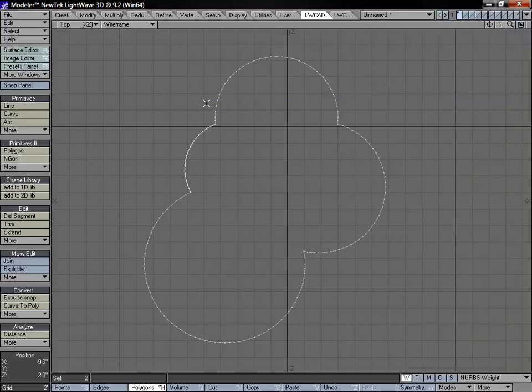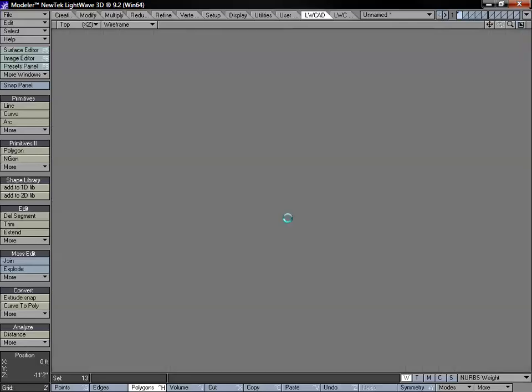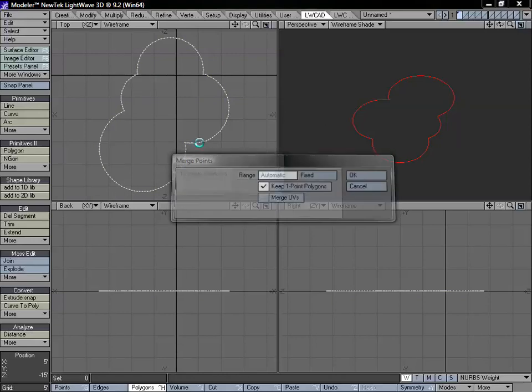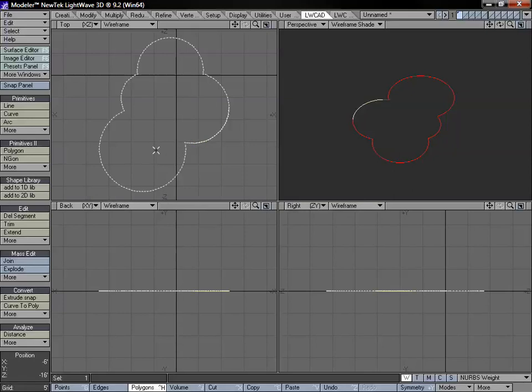Close that out. Now you can see we have these large polylines. So instead of just 2-point polygons, we have sections of different polygons. And a lot of that really depends on whether or not you've joined the tool together, or joined all your different objects together or not. And that can affect you in different ways. But you can always end up using the merge command to merge these points together and create one specific polygon. So I can merge right now, 13 points eliminated. You can select some larger areas. But overall, that's basically the same. I'm going to go ahead and delete.